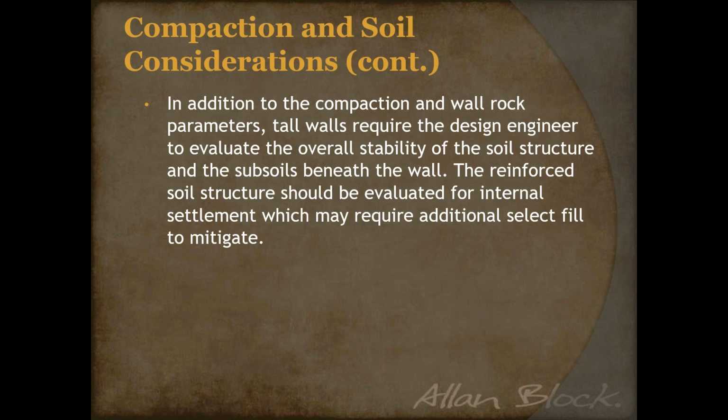In addition to the compaction, they require the engineer to evaluate the overall stability of the soil structure and subsoils beneath the wall. So that could be done through a number of different analyses. You can run a global analysis. You can run internal compound stability, which we're going to talk about, as well as typical internal and external calculations.